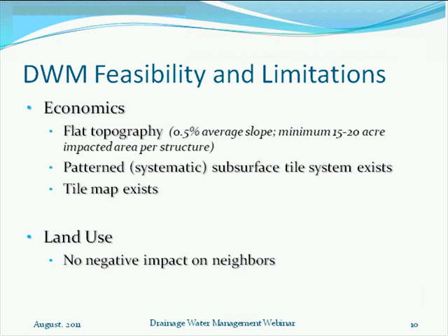So we talked earlier about feasibility of drainage water management. And so I think this is a pretty important concept, and let's talk about it now again. The big one is economics. If you have to build a structure every few hundred feet, that's not going to be very financially feasible. And so we say flat topography is the important thing.